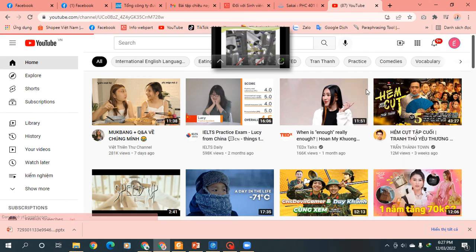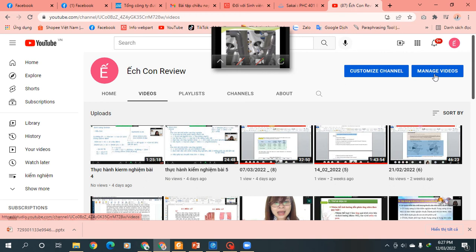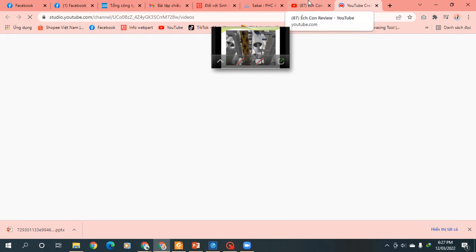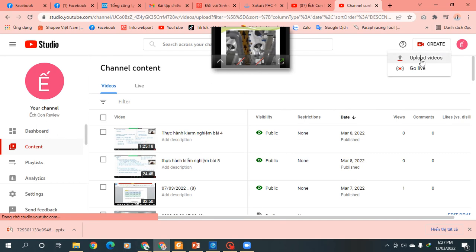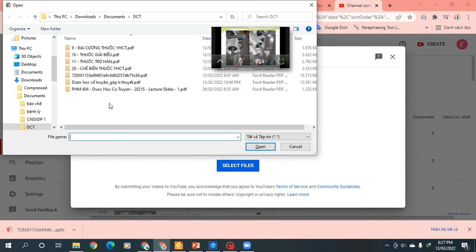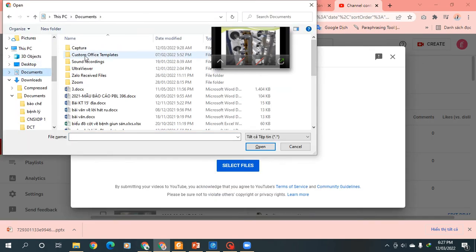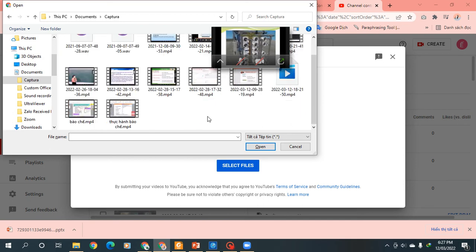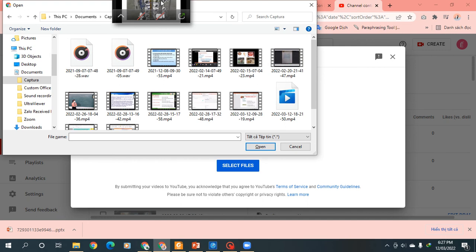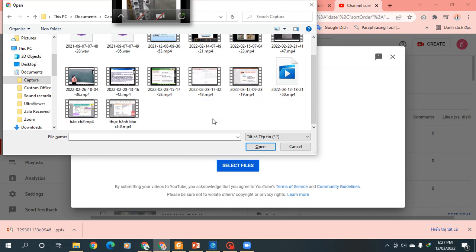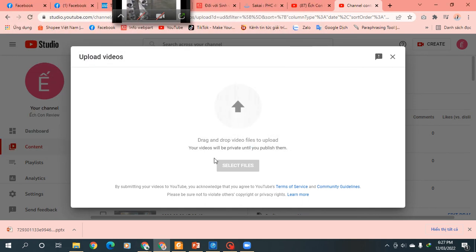Concentrate flow is the feed water from which water molecules have been removed, with the contaminants remaining behind. The concentration of contaminants goes up due to the loss of pure water. Therefore, this water is called concentrate as it exits the RO pressure vessels. Concentrate which exits the first stage pressure vessels is collected in the first stage concentrate header. The first stage concentrate passes to the inlet header for the second stage pressure vessels. Feed water for the 5 second stage pressure vessels is provided by flow from this header.